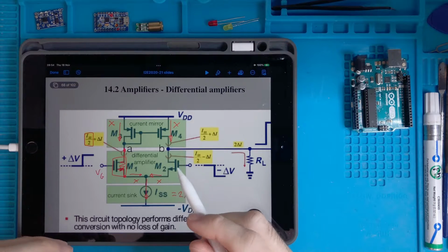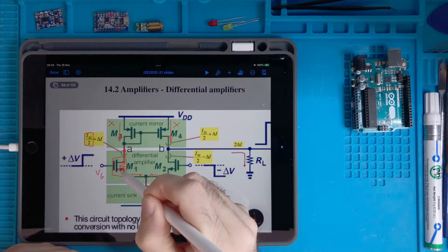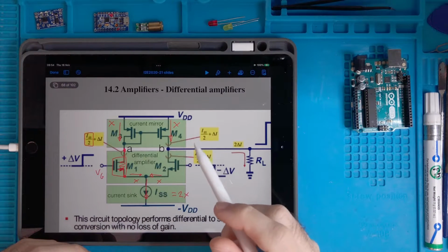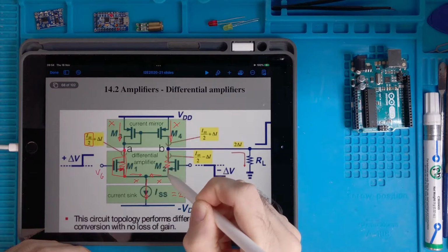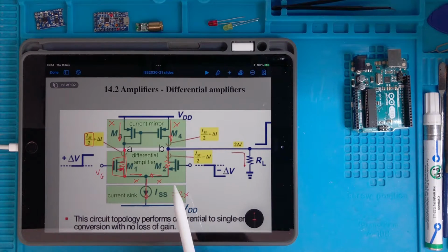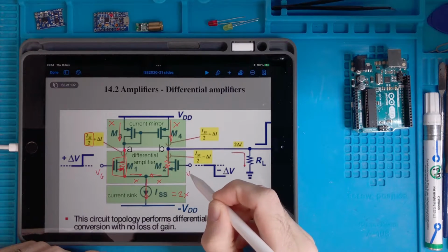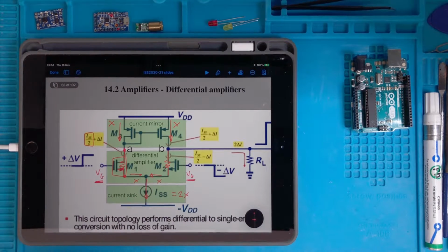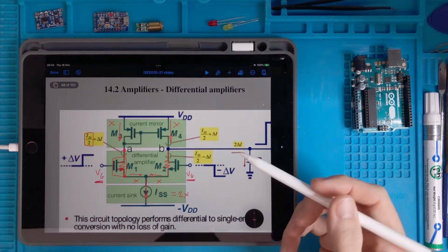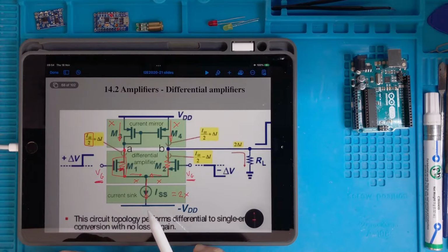And this happens when this resistor has a certain value, which has to match the value of the equivalent resistance of this transistor, which is of the same type as this one. So if we drive it with the same gate voltage here, VG, those two resistances are the same. So for this we are sure that this trick works.